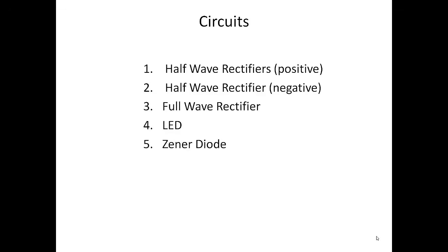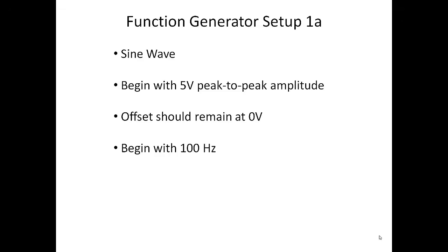For the Zener diode, we will be characterizing the voltage knee at different currents, and then we'll use them in a clipping circuit to show you how you can limit the input range for your signals when you're trying to protect the input of a circuit or an instrument.